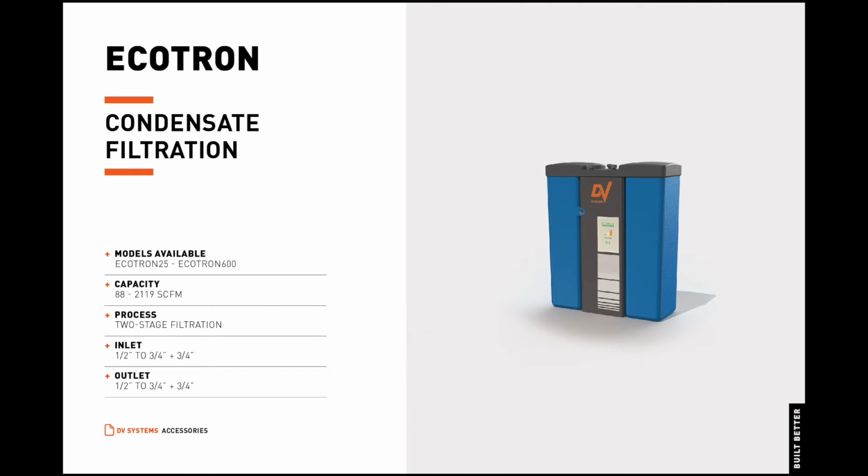The Ecotron condensate filtration system is a two-stage process that ensures that all contaminants contained in discharged condensate are effectively removed. The condensate discharged by our lubricated air compressor contains a significant quantity of oil and solid particles that will seriously pollute the environment if not removed. This mixture is classified as hazardous waste and cannot be discharged into municipal sewage systems unless the oil and contaminants